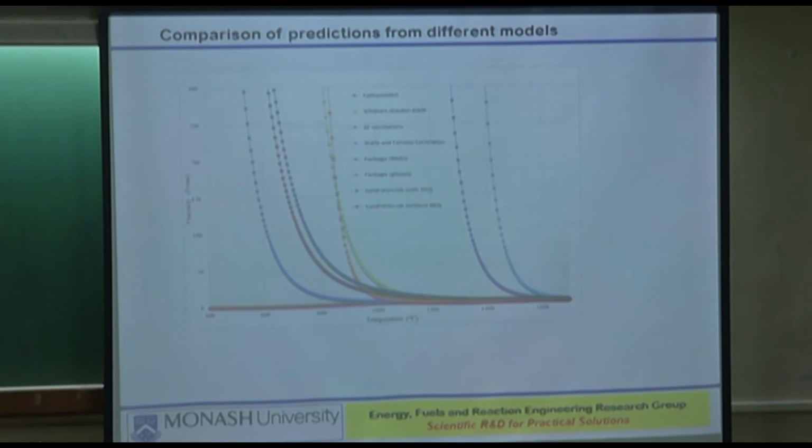But the last of the 4 ash fusion temperatures gives you the melting temperature, because that is what you can see when you put it in a hot stage microscope. You can actually see the cone gradually deforming and then disappearing into a liquid. Here, that observation falls between these two.